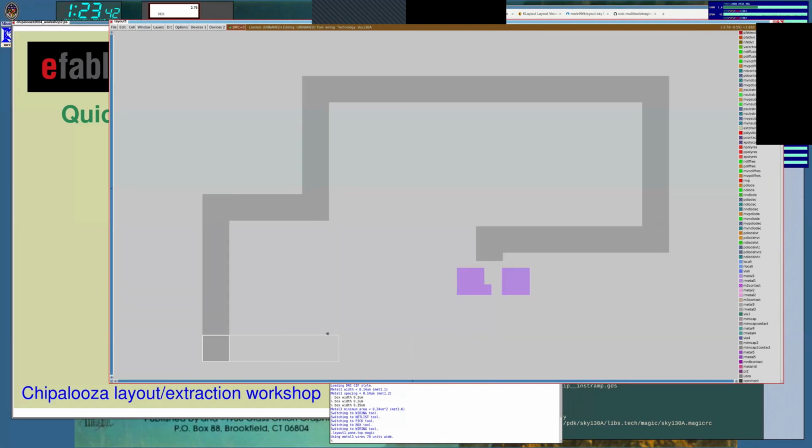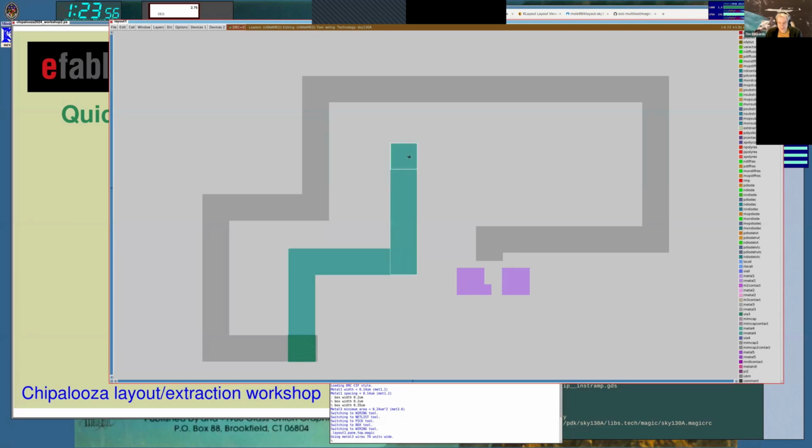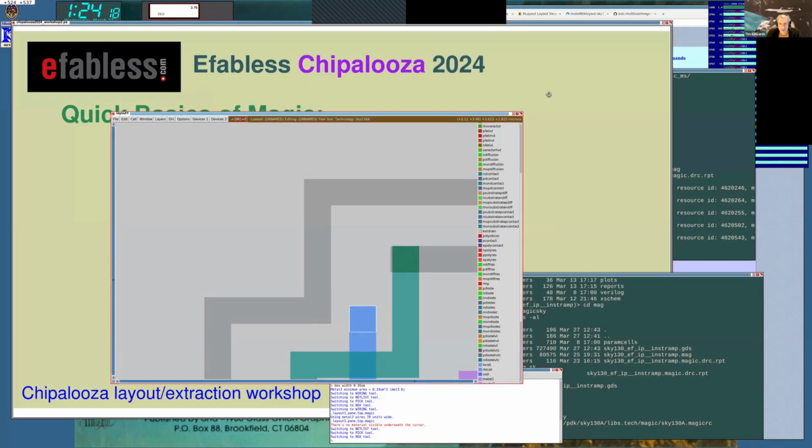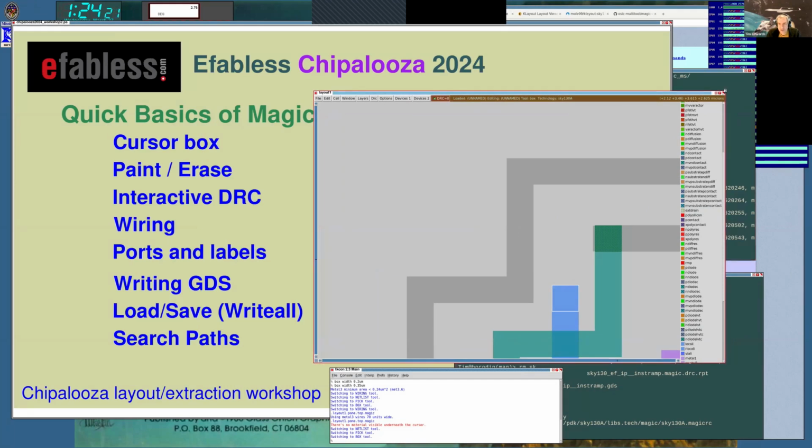Yeah, that's perfect. Now, if I want to, say, go up a layer, I can press Shift and left mouse button, and that takes me up a layer. If I go Shift and right mouse button, that takes me down a layer. So Shift down a layer, down to metal 2, Shift down to metal 1, Shift down to local interconnect. So this is the easiest way to connect everything together in a layout. And between that and the parameterized cells, I think is...